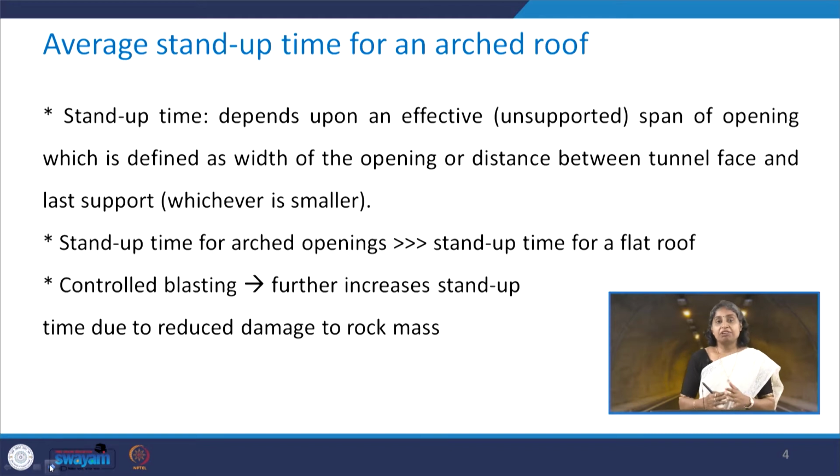First we understand what we mean by the stand up time. Stand up time is the time through which the tunnel can stand on its own, or the excavation can stand on its own, without the provision of any support system. So, in case the stand up time is more, we have a little more time for the installation of the support system after the excavation.